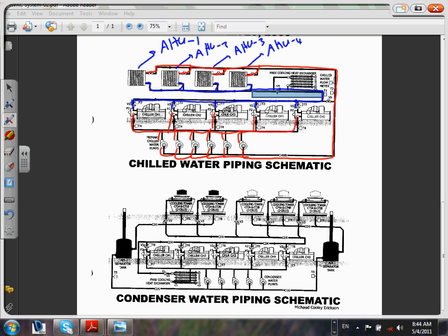Now, there's a lot of control involved in it. Depending on how much chilled water you need, you can accelerate the fans here with a VFD, guys, to control the cooling, or you can control the pump, how much chilled water gets into these air handling units, or you can shut down certain chillers. You don't need all 5 if you don't need all this chilled water. These are like parallel generators, Brad. If you have 5 parallel generators and the load went down and now you need 3, what do you do with the others? Shut them down safely through the control system.